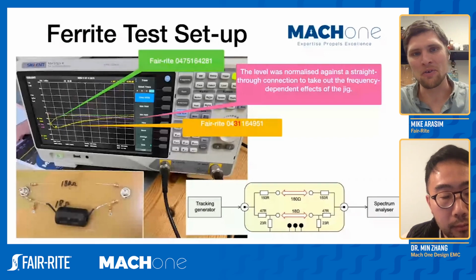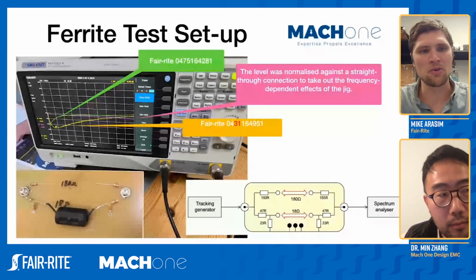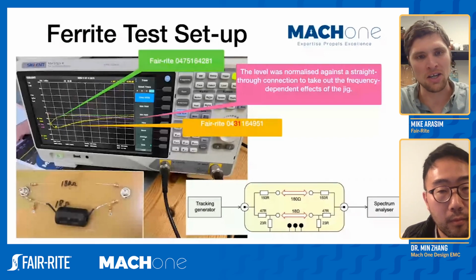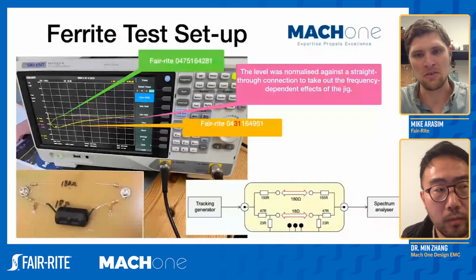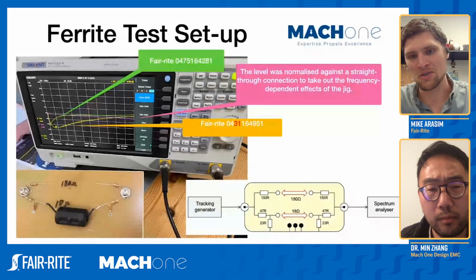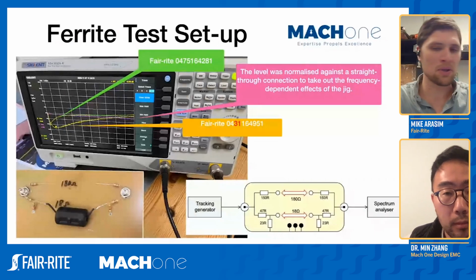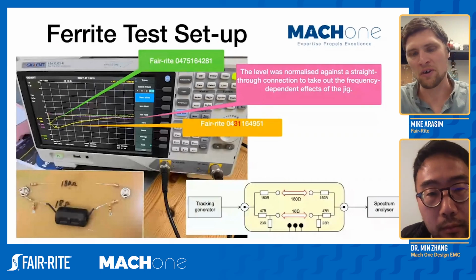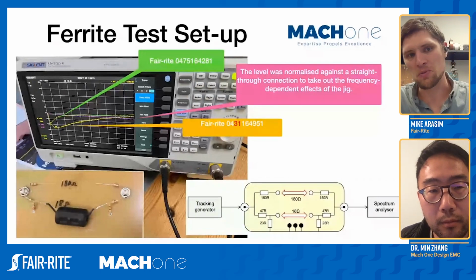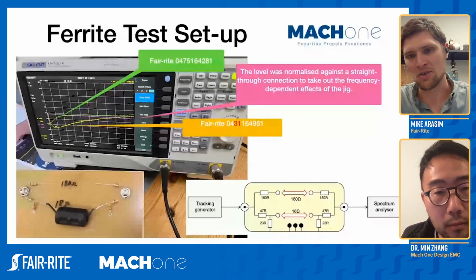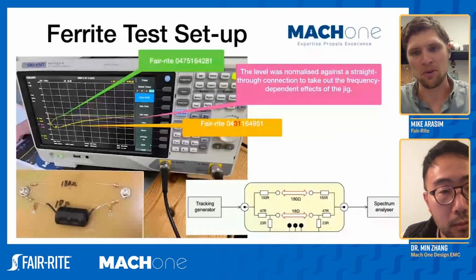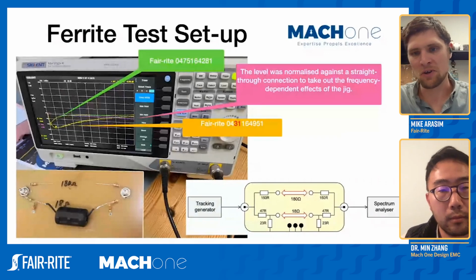Aside from that, a more similar test setup is what we do when we're characterizing some of the free space type devices. If you talk about something like a plate or the flexible ferrite sheets, then we switch to a vector network analyzer, and we're using different coils.